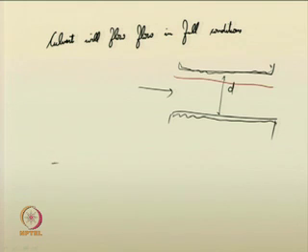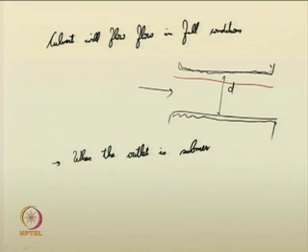For the following two cases, you have the inlet portion here, you have the outlet portion here. So, when the outlet is submerged, that is, if the water depth here is this much submerged, then you have a submerged condition, and the culvert may flow full.